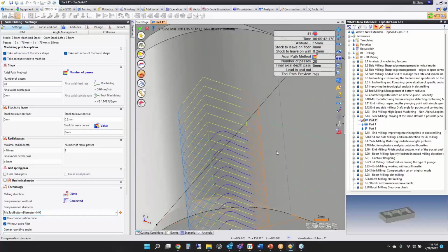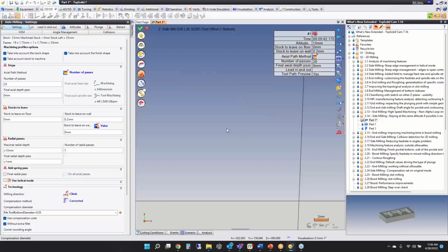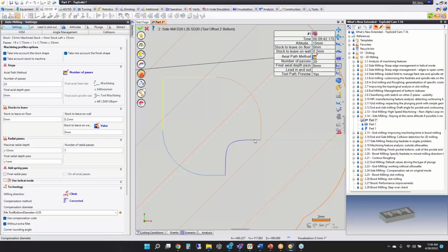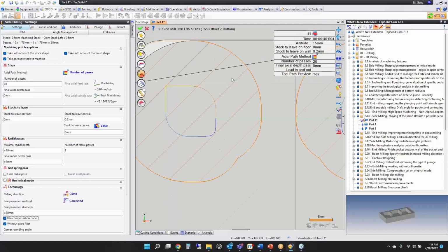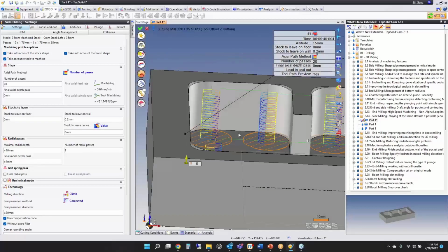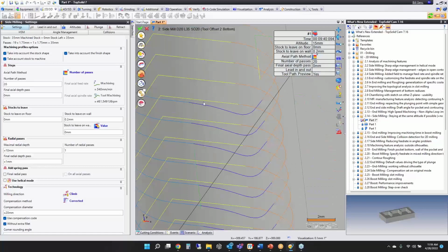Now, because of that, if we look at this straight down, you get motion like this because it needs to shift the tool path. Okay? It's still gouge free, but you're still making kind of a hard angle move there, right? So if you don't want that, get rid of this extra movement here. But in this corner, you're going to have a sharp corner because it's a size for size tool. So the only way to not have that sharp corner, obviously, is to put a smaller tool in, right? But now if we look at the link movement there between each depth of cut, it is extremely fast, extremely efficient, and extremely smooth.